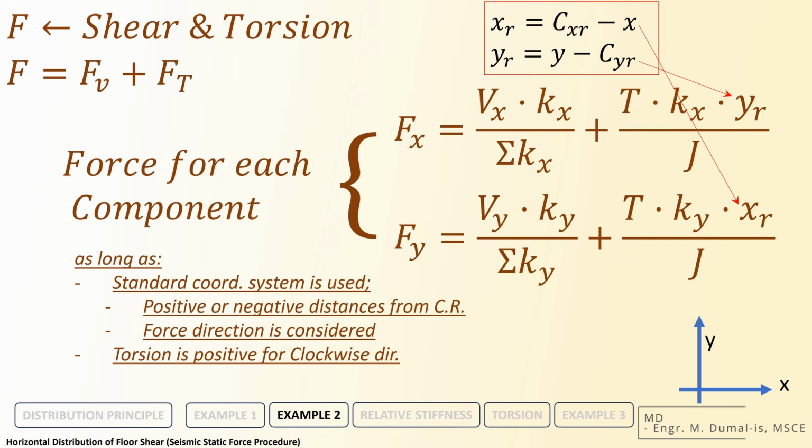The torsion's clockwise designation, combined with coordinate-aligned shear, guarantees that resultant forces, Fx, Fy, inherently carry correct signs based on their spatial relationship to the center of rigidity. This methodology is analogous to eccentrically loaded bolted connections in steel design, where positional logic dictates load direction. Let's proceed to apply this framework to our examples.